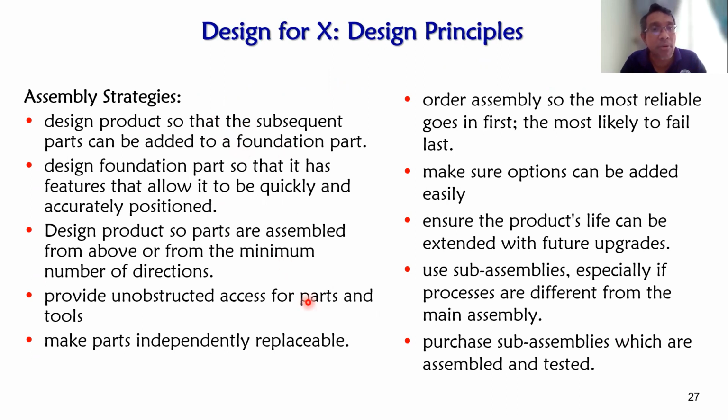So we need to think about designing the product so that the subsequent part can be added to the foundation part, design the foundation part so that it has features that allow it to be quickly and accurately positioned, and design the product so parts are assembled from above, from the top, using gravity features to easily assemble, and then minimize the number of directions, and so on and so forth.